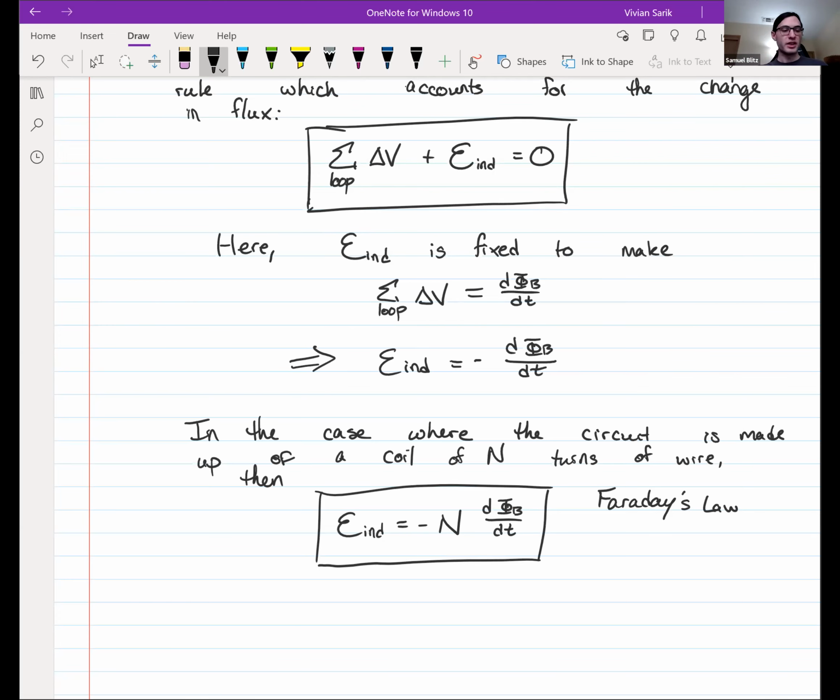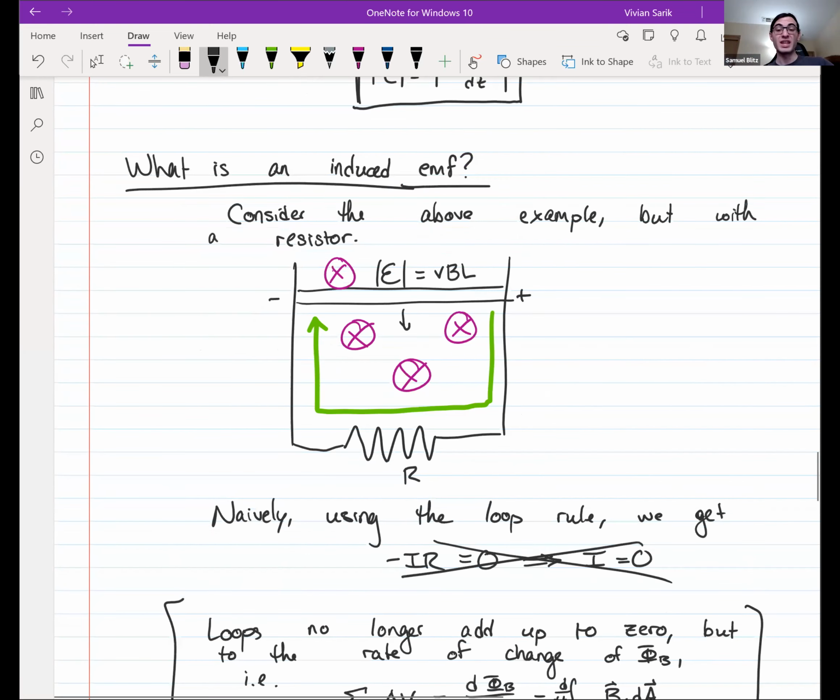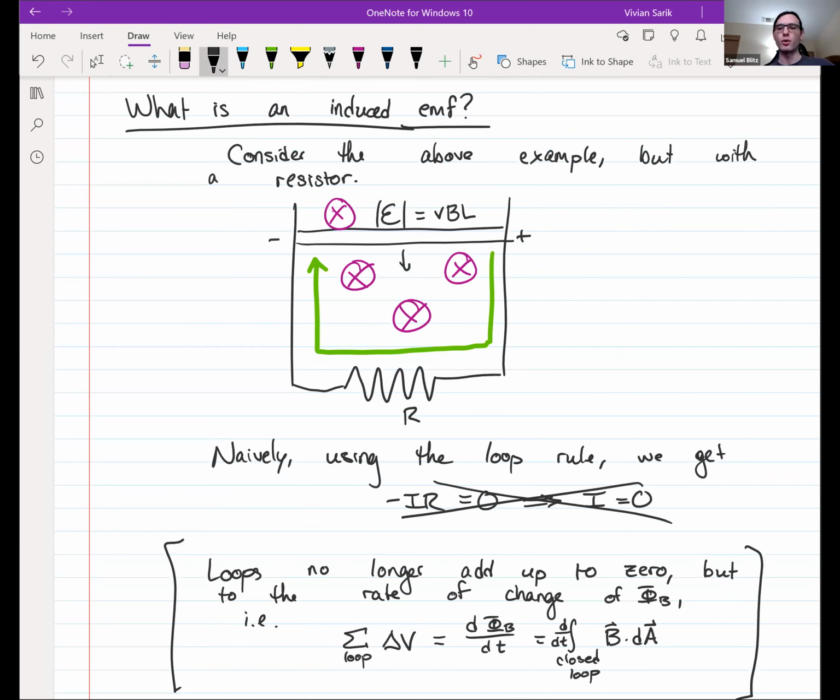Like I said, there was a lot of discussion of signs floating every which way: you induce currents in a certain direction, and the flux is changing in a certain way, and so on, which can be really confusing. Fortunately, there is a very useful rule of thumb to establish what direction the EMF points in, i.e., what direction it will try to establish current flow. The EMF established in this circuit, even if we didn't know what was happening, we could have established that it will create clockwise current flow just by noting the direction of the magnetic field and the way the flux is changing.